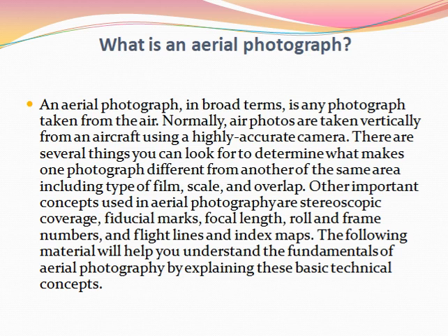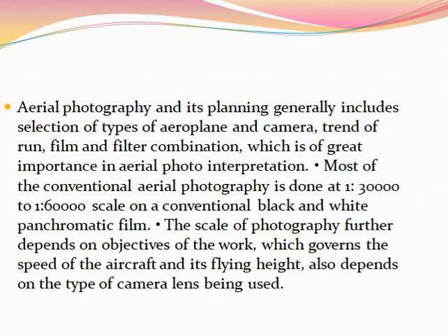Then topo sheets, or topographical maps. They are prepared by the Surveyor General of India, Dehradun. In this, the scale used is 1 is to 25,000. It shows roads, tracks, streams, water sources along with the contour lines and physiographic features.